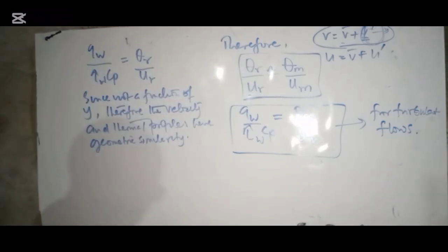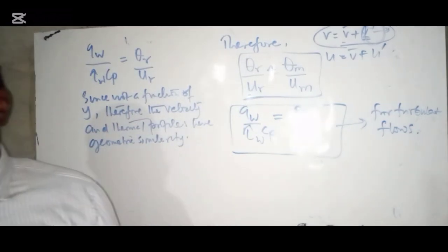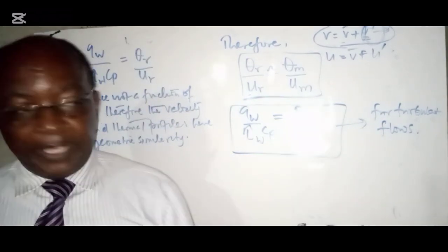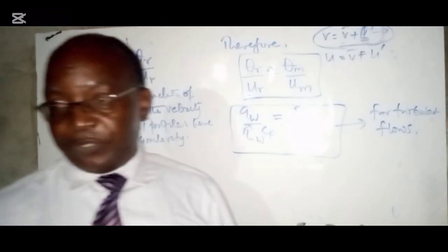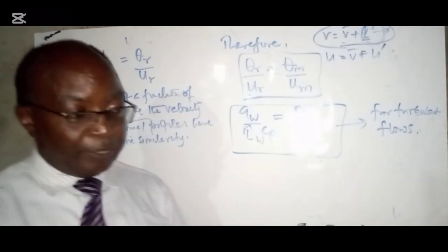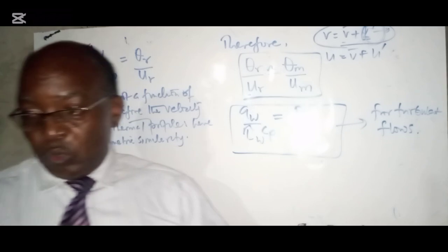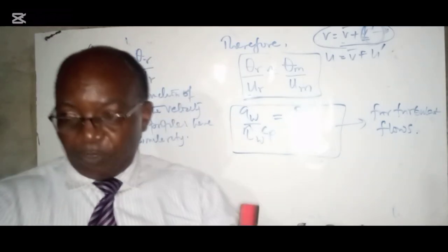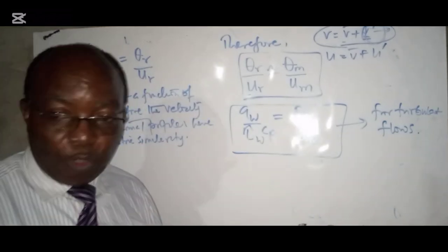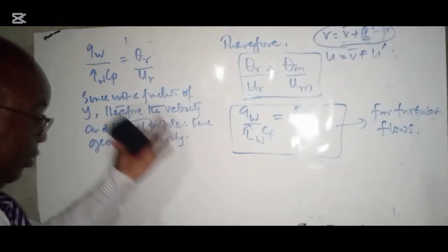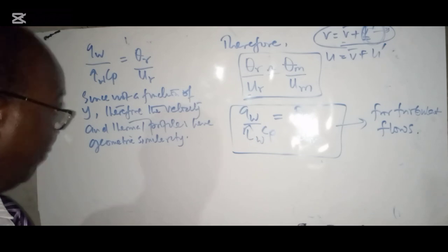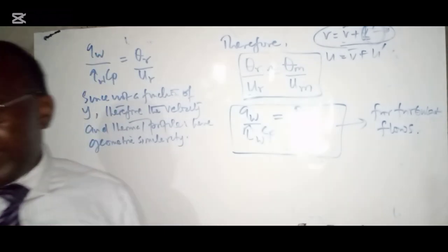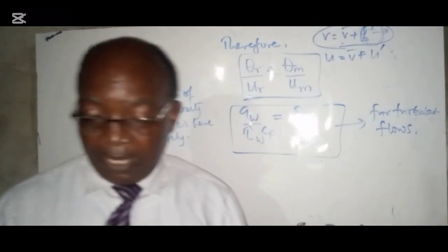This can be used for turbulent flows. Very good. In summary, we built up from the Reynolds analogy, where we have the rate of heat transfer to that of the shear stress, with expressions so that we're able to work with smooth surfaces. We gave the expression for the plate surface, and we got expressions in terms of shear stress.